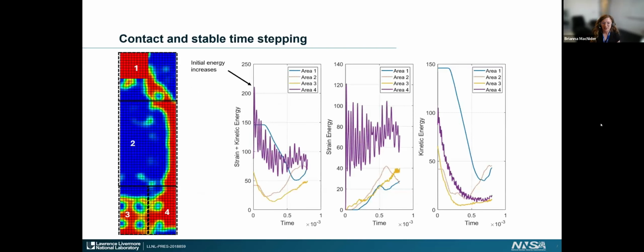I mentioned there's an asterisk on that stable time step from the previous slide. This asterisk comes from the contact condition that I described, which we were prescribing along the bottom of our domain here. Over here on the left is some intermediate optimized design, not converged. It doesn't matter a ton, except that if you look at that bottom boundary, you can see part of it has fully dense material as we started off with, part has very low density, and part has intermediate density material.